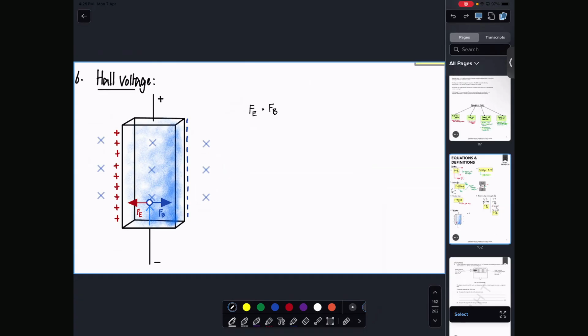That process that we just did is called calibration. Calibration is basically giving meaning to the number using the setup that you are aware of, and you use that to set like a graph or something, and then rest of the place where you place it, you can use that as your reference. Okay. So all Hall probes need to be calibrated before you use them because you're making them. They're not standardized devices.